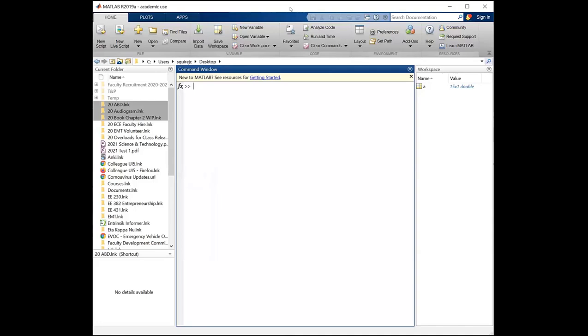We've already found what the DTFT is by hand using in the example with those summations, and now we want to graph it. And in words, I'm going to try to just say what it is so we don't forget it. It's 3 over 1 minus 0.5 times the exponent of minus j omega, and all of that is in the denominator. So this was what our DTFT is. We want to figure out what it looks like.